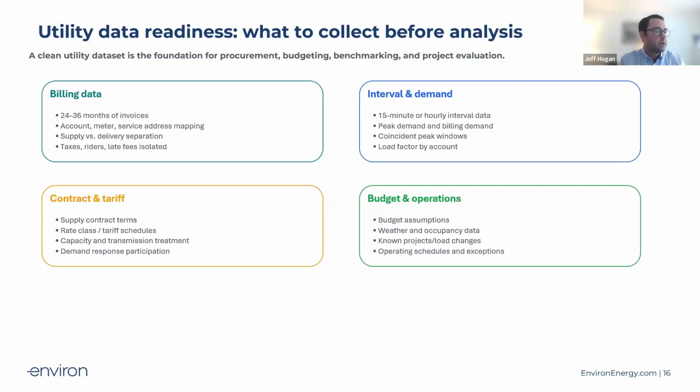Demand response is something that we feel a lot of organizations participate in. So how you participate, what the financial obligations are, does that need to be factored into your budget? Where does that check go? And then ultimately, just your budgeted assumptions. Ultimately, what are we projecting from a heating degree day and cooling degree day perspective, if you want to get to that level of granularity? Occupancy can be a relevant data point. You could look to correlate potentially patient days to energy use to see if there is some type of correlation through a regression analysis.